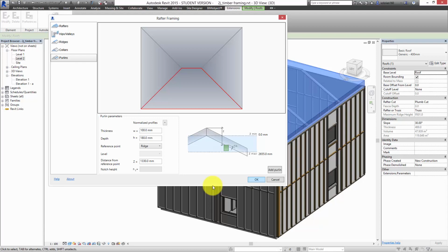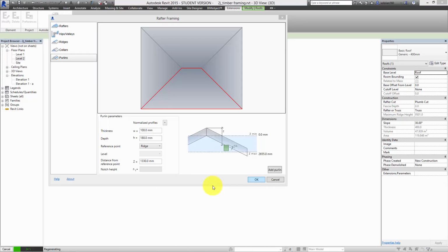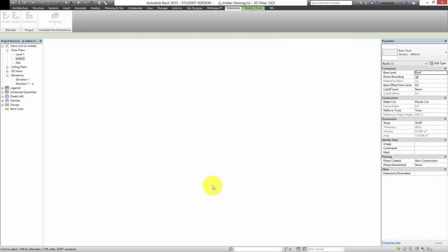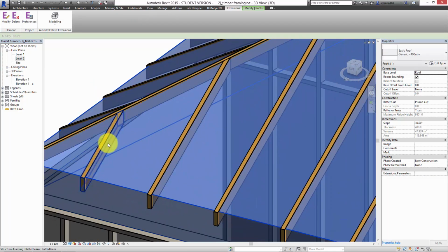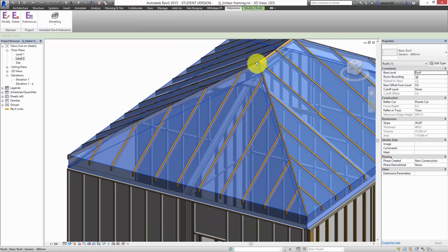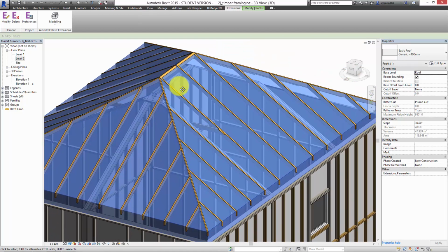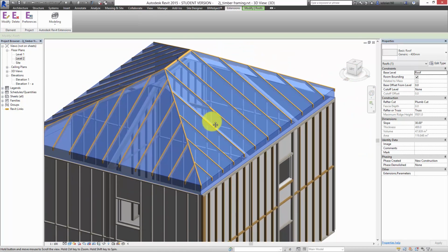And even though it generates the beginnings of a nice roof structure, it's got the same issue. It generates the roof structure at the very, very top plane of the roof. So if you've designed a roof here that had tiles at this level here, it's not going to generate your structure at the correct position down here. It's going to generate it at the top plane. It's completely stupid. So even though it's got a lot of information here that we can use, we need to be aware that it's putting it in the wrong place.